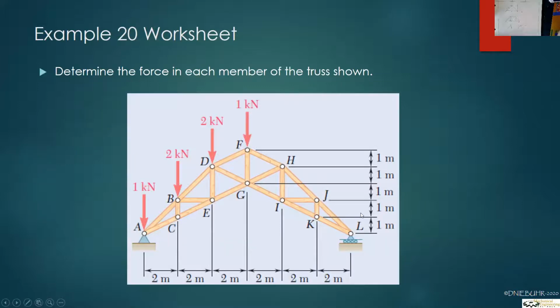Now, this is not a symmetrical truss because the loading is heavily weighted on the left side, not on the right. So you can't really use any of the information from the left or the right, but because those internal members are zero force, it does make the calculation quite easy. So let's do a few of those just to show another example of this type of truss. This should get you well prepared to do the homework.